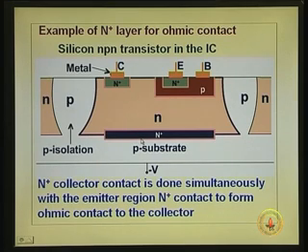20 years back, it must have been 20 microns. Now, it is way down to 1 to 2 microns. Okay, that is the n layer, which actually is a collector region. Now, after that what you do is, you want to have the transistors isolated